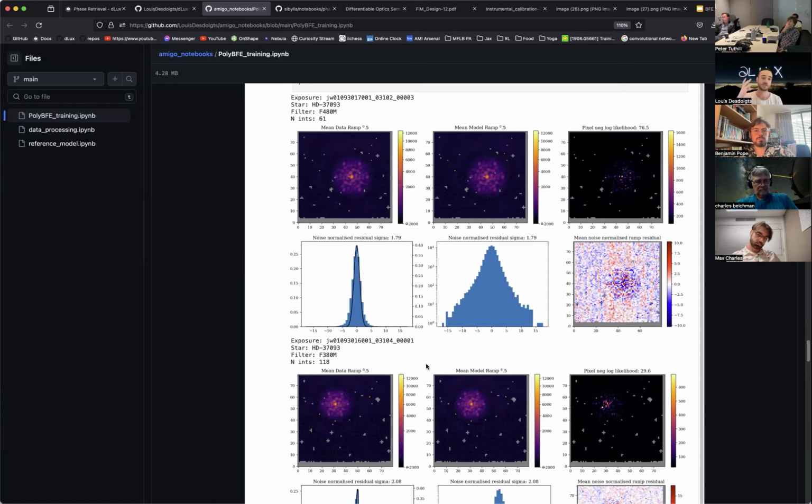The last step in stage 1 is they take the up the ramp reading and fit a slope to it, and that's your brightness value for that pixel. However, if you have charge bleeding into or from a neighboring pixel, those ramps are no longer straight lines. They're curved, right?